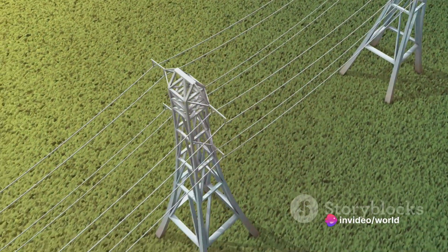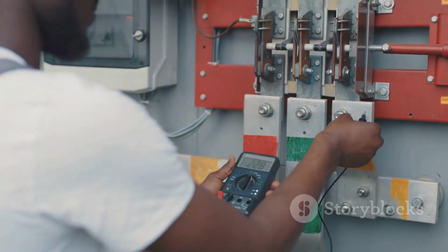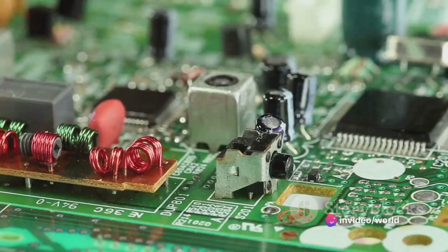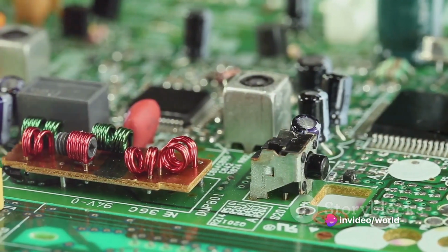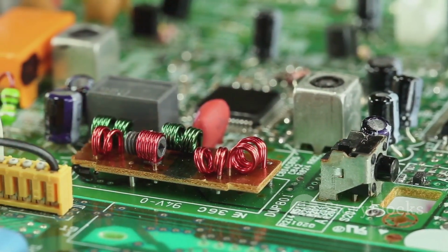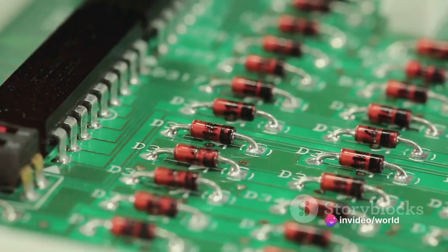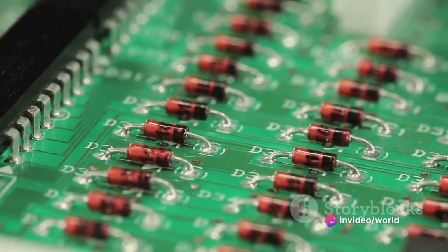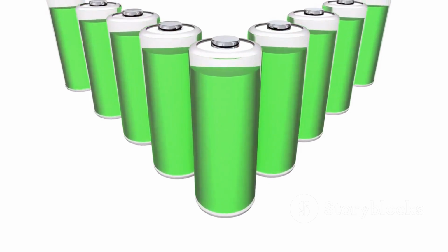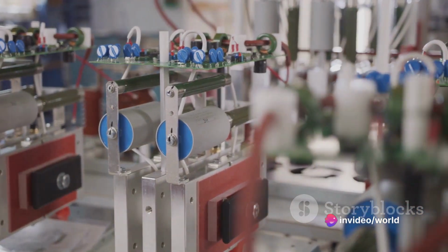Next, we have power factor correction. In alternating current power systems, capacitors correct the power factor, making it closer to 1. This increases the system's efficiency, reducing energy loss and improving the stability of the power grid. On to filtering. Capacitors are the sieve of electronics, filtering out frequency components in signals and power supplies. They're like a coffee filter, letting the good stuff through while keeping out the undesirables. In timing circuits, capacitors, in conjunction with resistors, create time delays for processes like blinking lights or timing intervals. Finally, in energy storage systems, capacitors store and release electrical energy quickly, like a sprinter bursting out of the blocks.